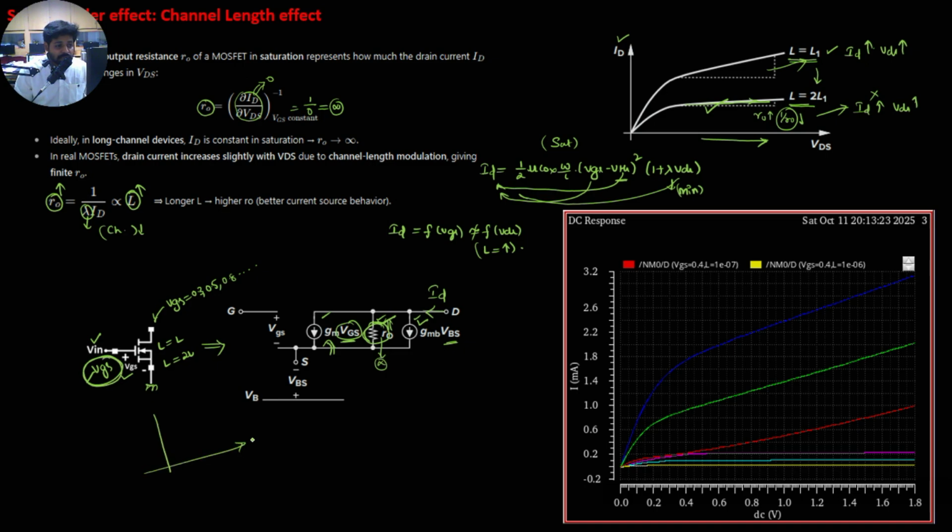As VDS is changed, once the transistor enters the saturation region, at VGS minus VTH, the current should be maintained constant. So if it rises like this as VDS rises, this is the problem where we lose the VGS control. We cannot use it for better applications, since it is not good for analog applications.